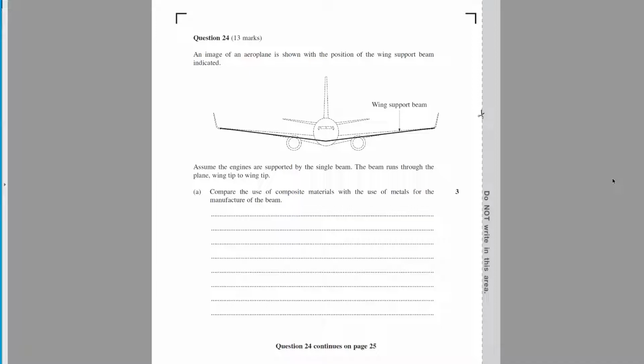Now, if you wanted to watch more, you could. Real Engineering has a video where he talks about why the Dreamliner's windows are so big, and how, because of the changes in air pressure, the fuselage of the plane actually expands and contracts a lot. The point of weakness where failure is likely to be is in windows, which is why windows have a rounded shape and tended to be smaller. Whereas with carbon fiber, we know they have much better fatigue resistance, which is why we can have bigger windows on the Dreamliner. The big windows have both a passenger comfort and a safety feature.